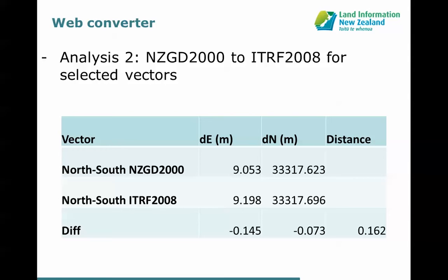Now what I'm wanting to look at in a little bit more detail is what the effect might be on the relative accuracy of our project area, because that's usually what we're interested in. If the difference between datum 2000 and ITRF was the same in all cases, then it probably wouldn't be too much of a problem, even if it was really large. If all 4 of those points had all moved by 100 metres, that would actually be fine, because relatively all the measurements you make would agree with those coordinates, and it's that relative accuracy which is generally of most interest.